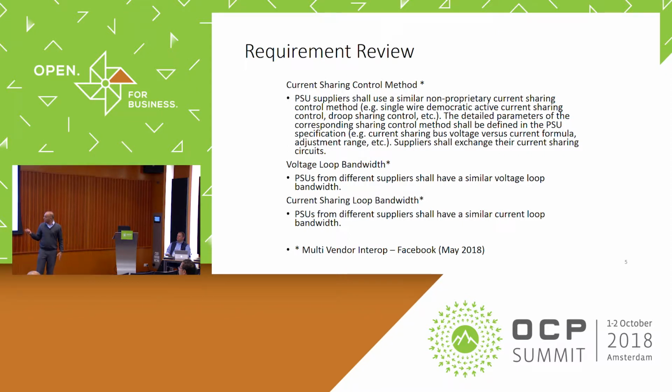Some of the key things that we looked at were, if you take two power supplies, even though they will both be, let's say, 5 volts, 20 amps, they are really different. Their current sharing is not the same. The transient behavior is not the same. And when you insert them into the shelf, you may find the tolerances may be different for those power supplies. And EMC behavior is another thing, right? They may behave differently in terms of EMC. So we run into a lot of challenges to that effect. So we got this document as a starting point.